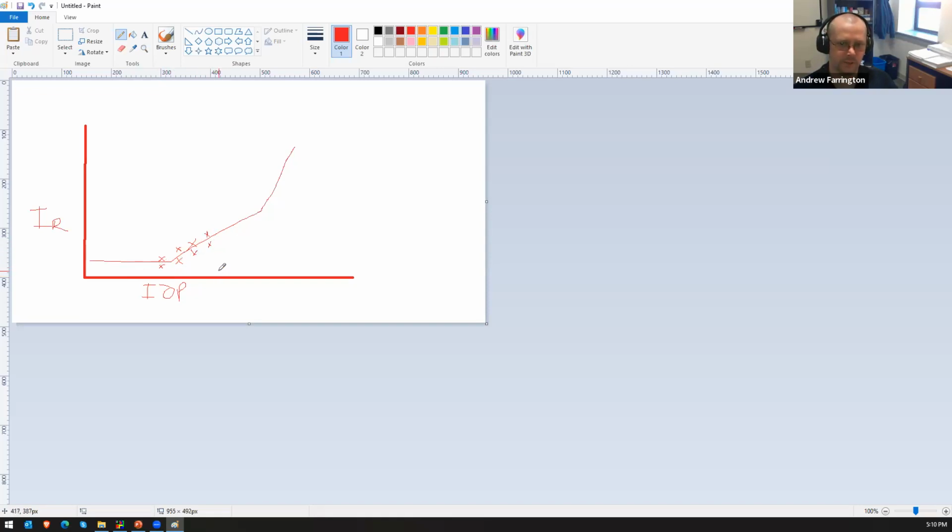And so it'll continuously ramp up the operate current or the restraint current as needed until it gets to the line, and then usually the test results will give you a plot, and it should look exactly like this line. It'll show you where that point is that it tripped, went from the restraint region to the trip region.